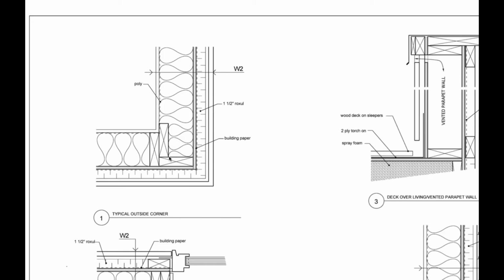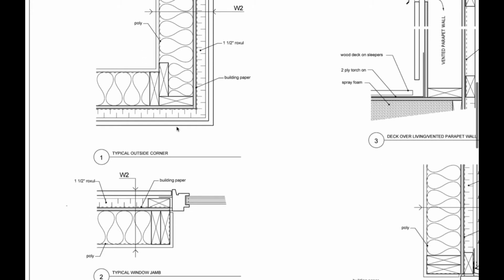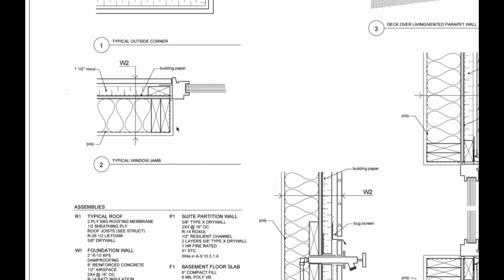And they just give a typical corner. This is a really standard corner that you see in framing so that you can maintain insulation all the way through the corner, which is great. If you do it in different ways, you can actually trap it so that you make a space in the corner where there's no insulation. That's going to be a cold spot, which is no good.